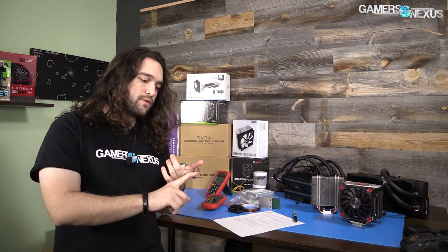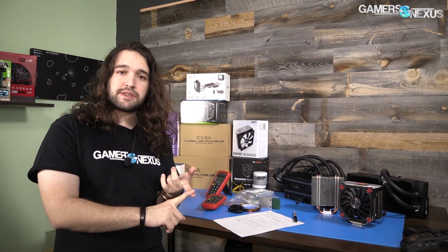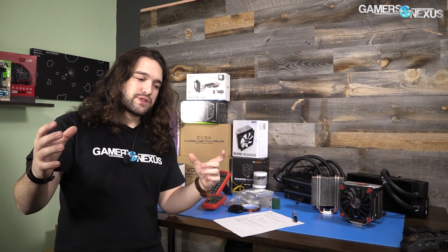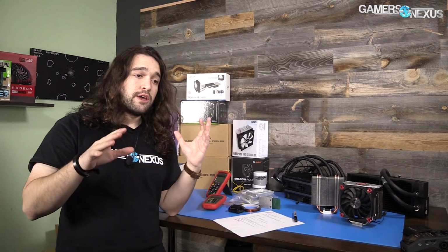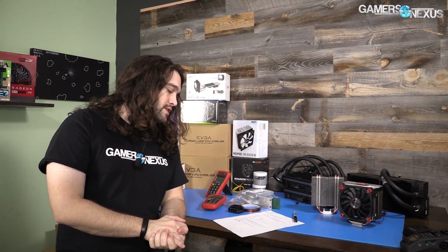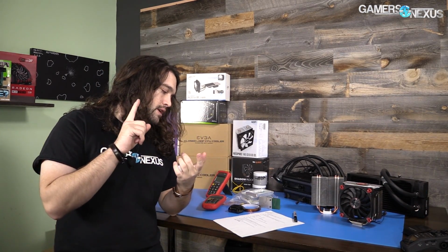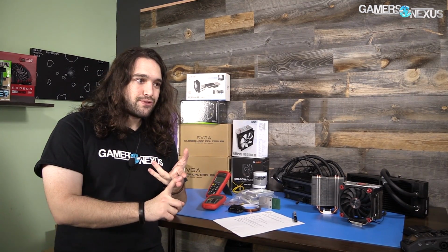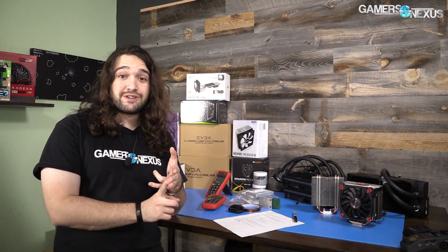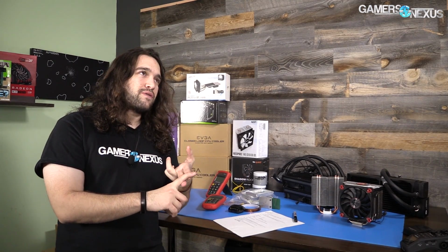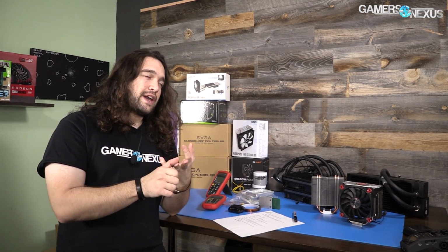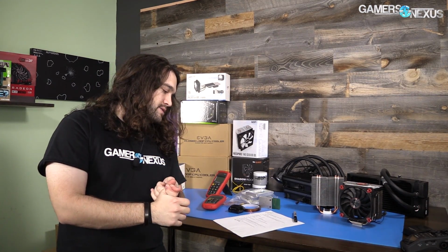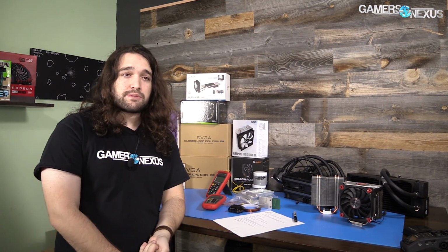But you have to control for, one, it's got to be the same video card. So if you're changing coolers, pick a reference board, pull the reference cooler off, put it on whatever you're testing, use the same card, and then you've also got to control for, of course, the frequency. You have to control for boosting. If it's a Pascal card, good luck. That's a lot more difficult. Control for voltage, fan speed, power draw, and temperature thresholds and things like that that could impact performance.